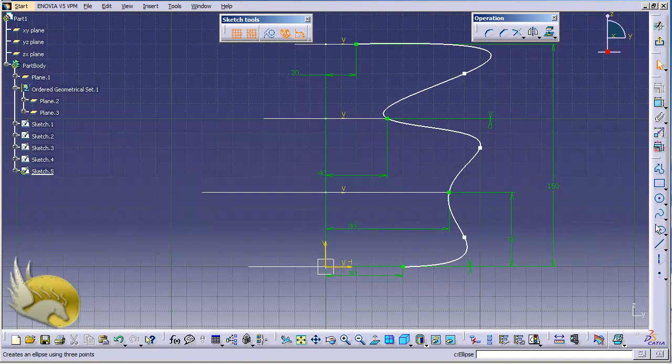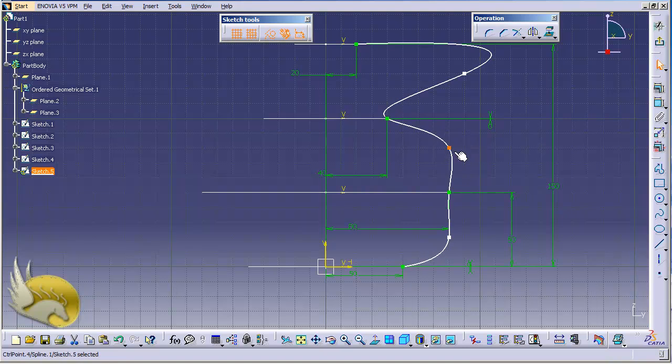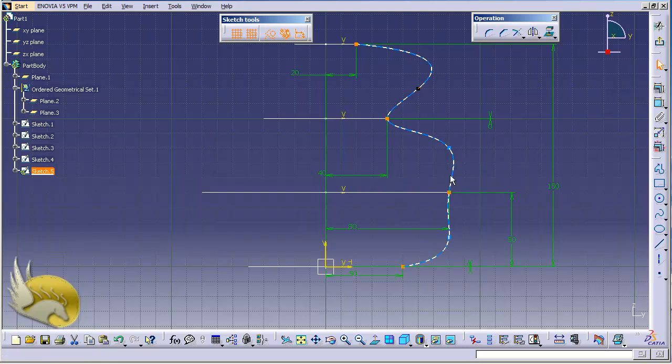You should make sure that whenever you rotate this, it doesn't create a cusp. That means it doesn't cut itself. So to do this, I'm going to select these points and move them to where I want. I can of course create some constraints for these, but this is okay right now. So this is the shape that I need to have, for example. Of course you can change this to your desire. Just make sure that it doesn't cut itself whenever it is going to be rotated.